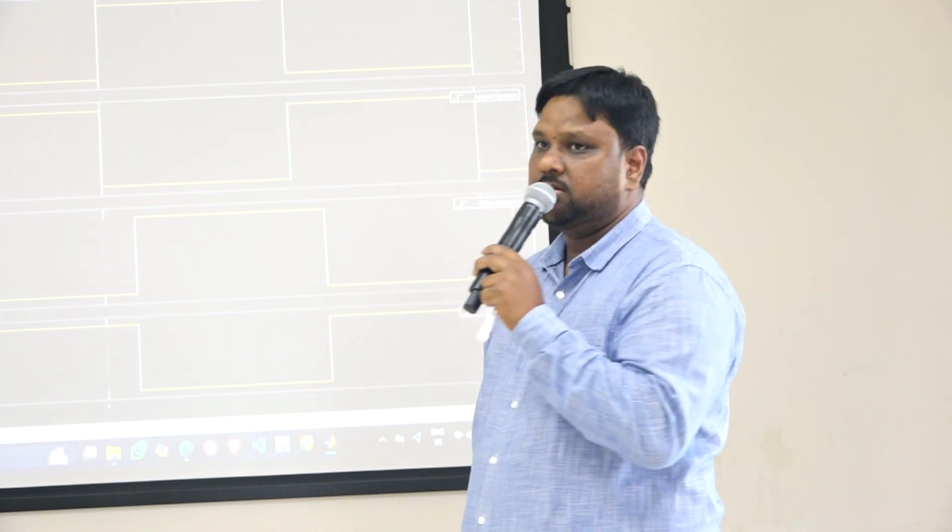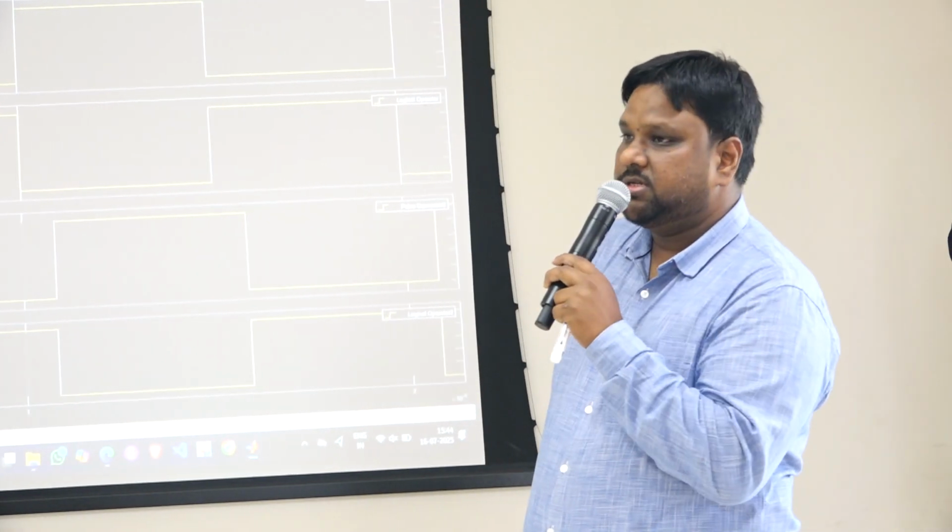The S5, the first signal and third signal, see the starting point, there is a phase shift of 30 degree. Correct? And the same signal is inverted for the switch 6 and switch 7. Understood? This is the operating principle of DAB converter controlled through single phase shift modulation scheme.